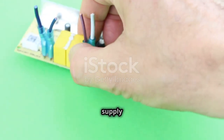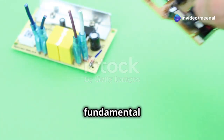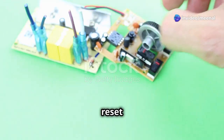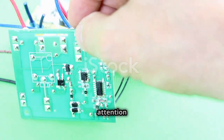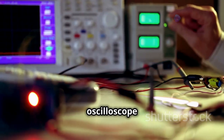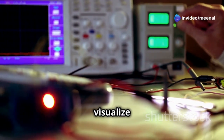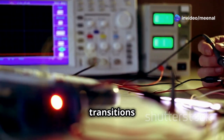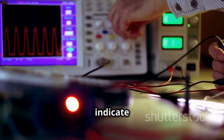The power-up test. Connect your device to the power supply and observe the reset signal. This initial test is fundamental, as it verifies that the reset circuitry is functioning as intended right from the start. Pay close attention to the behavior of the reset signal during this phase. Use an oscilloscope to monitor the voltage level during power-up. The oscilloscope will help you visualize the reset signal and ensure it transitions correctly. Look for any irregularities in the voltage levels that might indicate a problem.